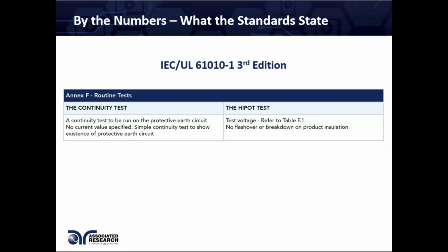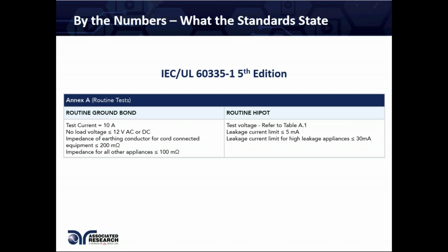But as we look at some of the next slides, you learn that the key differences between a ground bond test and a ground continuity test lead us to lean more towards running a ground bond test, even on fully assembled products. A 1-second ground bond test, for example. Some other examples from standards. This one is, now